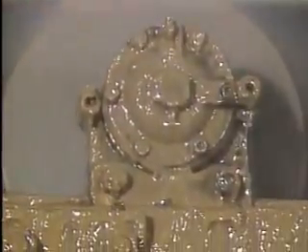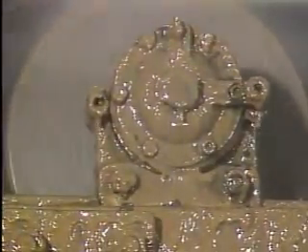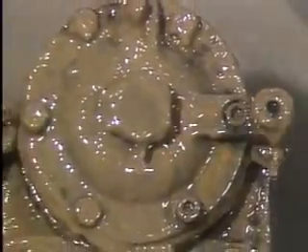Additives can also protect against corrosion due to contact with water. This bearing housing is constantly exposed to hot water vapor. Water works its way into the bearing and contaminates the grease. To keep the water from collecting in pockets in the grease and corroding the bearing, a water-stabilized grease is used.